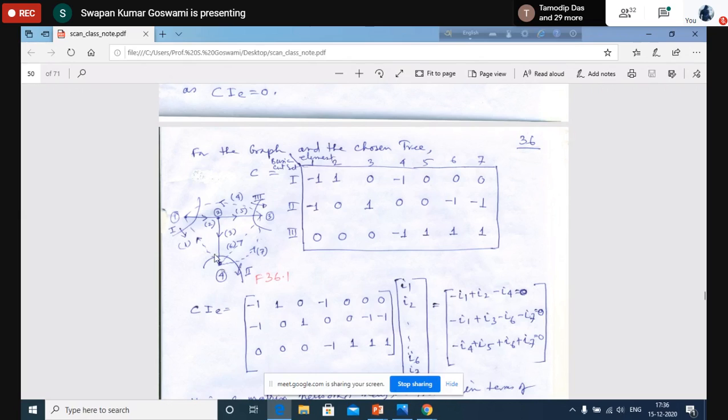In the other part you will have the remaining elements 2, 5, 4 together. So this is one subgraph. Node 4 is forming another subgraph. So removing these four elements is dividing this connected graph into two connected subgraphs. That's why these four elements together form a basic cut set. And this is a basic cut set because in these four elements, only element 3 is a tree branch. That's why it is a basic cut set.